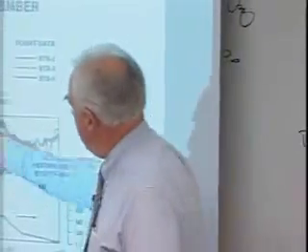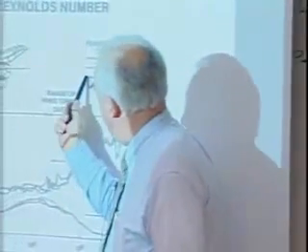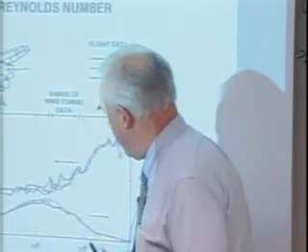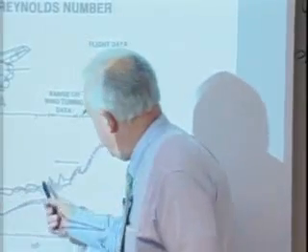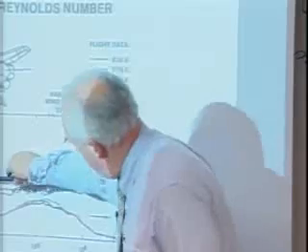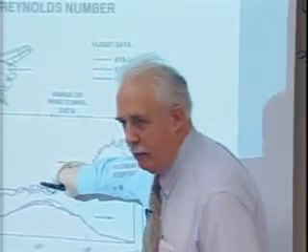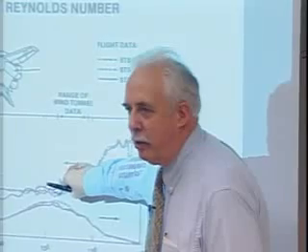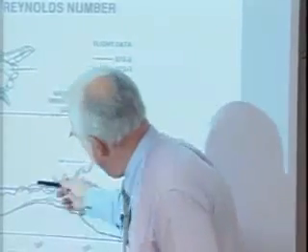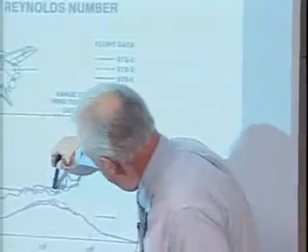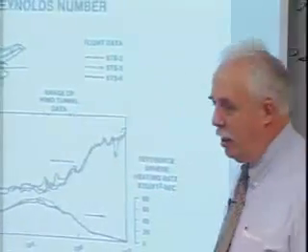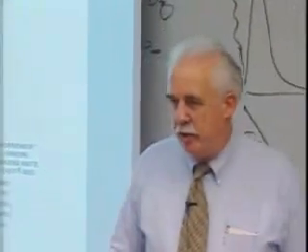In any event, this is heating on three trajectories through normal shock history. It's sort of like time. 3 different vehicles. This is to reference heating. Okay, this is our old Apollo level technology. It works quite well all the way through to peak heating, and then it starts to change as the Reynolds number picks up and the wake characteristic changes.